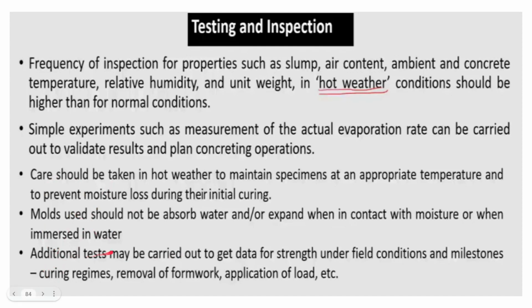Otherwise the concrete shape is disturbed, and that also results in some cracks. Additional tests may be carried out to get data for strength under field conditions and milestones, curing regimes, removal of formwork, application of load, etc. Some additional tests may need to be carried out for gaining all those data, mainly dependent on the trial.